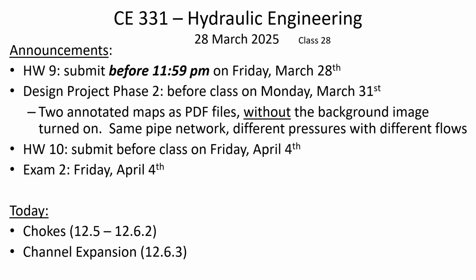All right. So we're still in chapter 12. We're learning how to use the specific energy method to answer lots of questions like, what does the water do when there's a choke? Or what does the water do when the channel gets wider? So neither of those could be answered with Manning's equation. Manning's equation only tells you what happens when conditions are steady and uniform. But if there's some sort of a disturbance that causes the flow to deviate from steady uniform flow, we need to use other methods like specific energy analysis.